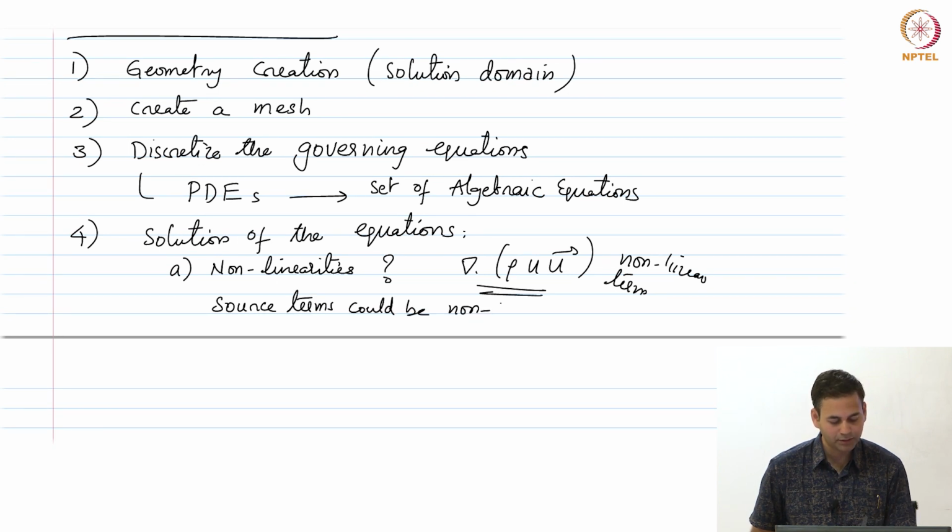What other things can be nonlinear in a simple diffusion problem, a simple heat conduction problem? I think we had this question before, right. So, what about thermal conductivity? Could that be a nonlinear function? It can be, right. K can be a nonlinear function of temperature, in which case we have to account for the nonlinearity that we are getting, okay. So, essentially the coefficient of diffusion, as we will call it with a general name, could be nonlinear as well, right.